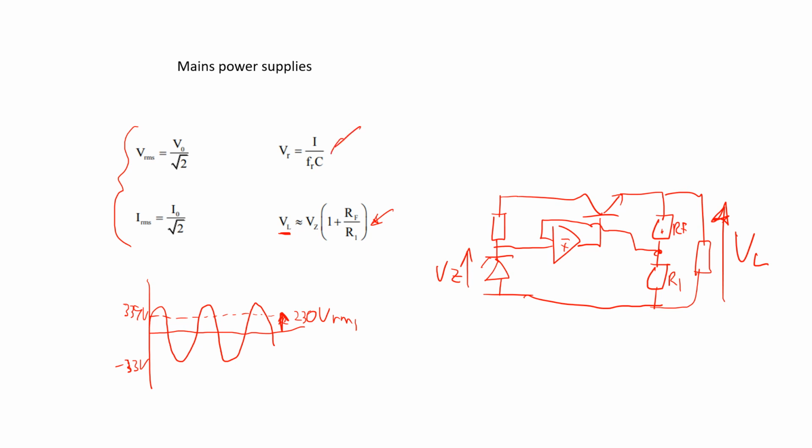This one's about ripple voltage. So half wave rectifier. If you've got your thing like that, there's a half wave rectifier. It might go up and down like that, up and then down like that. Then this bit's the ripple, the voltage across the ripple. So you can work that. That's current, by the way. That bit there is current, not one. Frequency of the ripple would be 50 hertz, or if it's full wave, it would be 100 hertz because you have twice as many ripples.